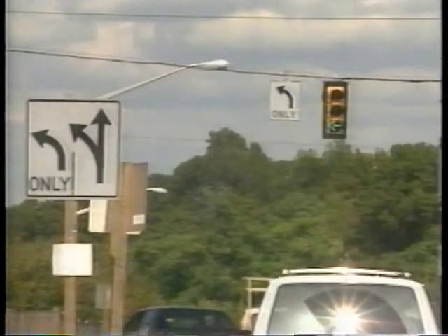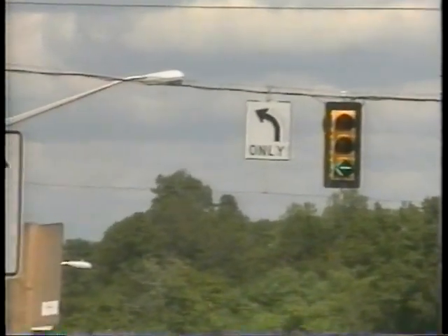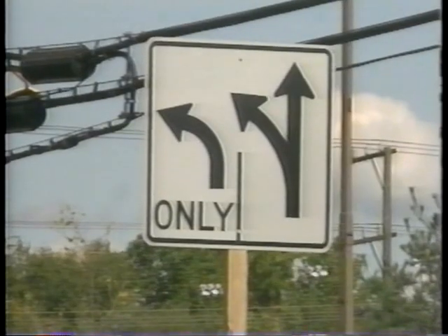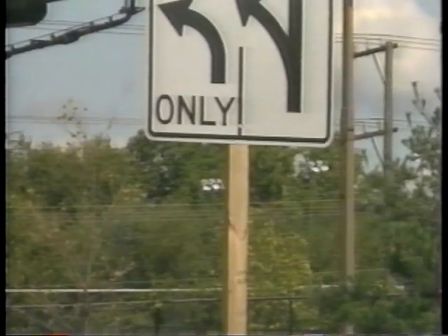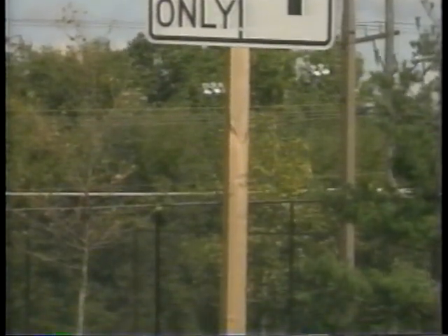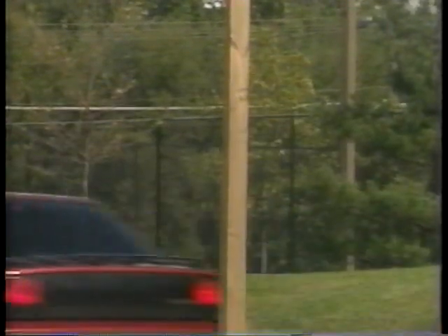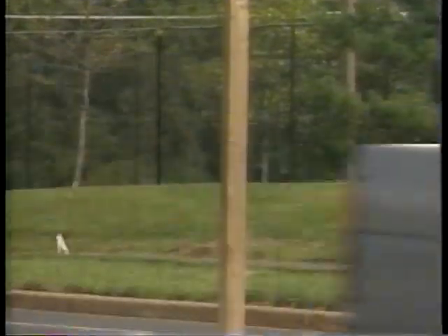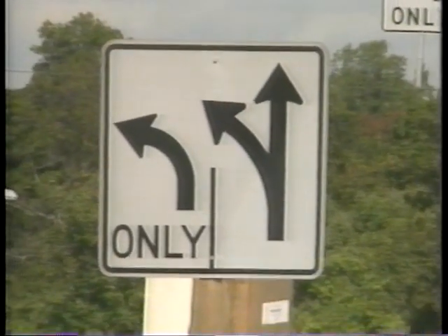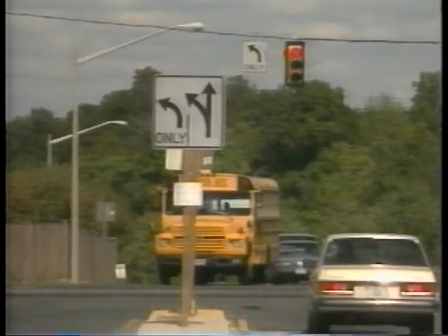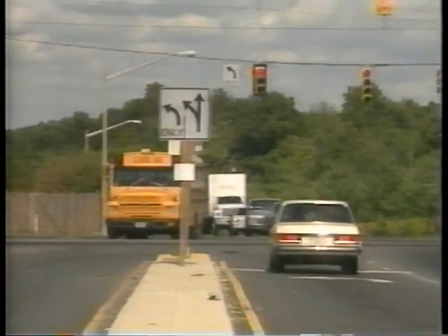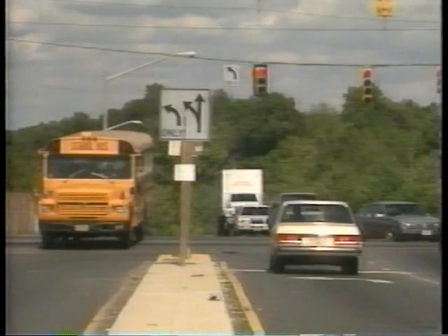These signs are used for safety in single lanes or to control dual lanes and increase the capacity of an intersection. They may be mounted on posts or over the lane they apply to. A post-mounted double turn sign should be located on the right curb for double right turns and on the left side of the street for double left turns.